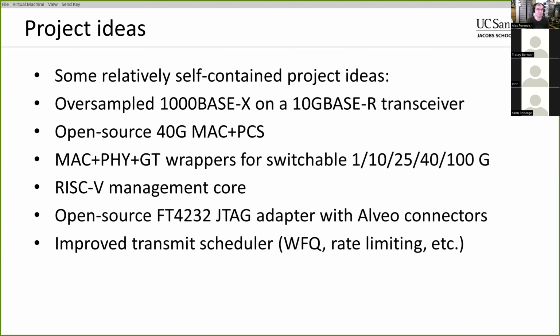The idea being to make it so that if you're implementing Corundum on a new board, you don't have to make any modifications to the device driver. So both the Linux kernel driver, the DPDK driver, any other third-party drivers that somebody might write, they don't have to be aware of what the actual board is, because they can just talk to the soft core using a standardized protocol of some sort, some sort of board-independent API.